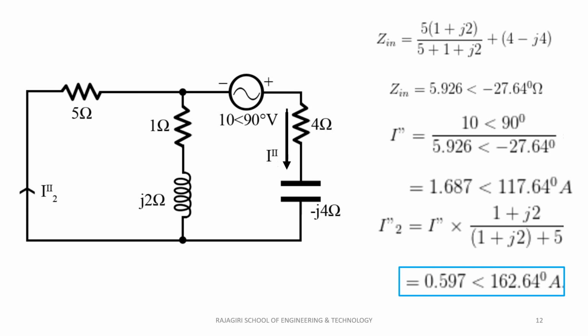To summarize, we have learnt to state and prove the reciprocity theorem. In a nutshell, the theorem tells us that when the cause and the effect are interchanged in a passive linear bilateral network, the magnitude and the phase of the effect remains unchanged. This holds good for both DC and AC circuits.